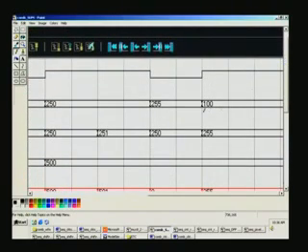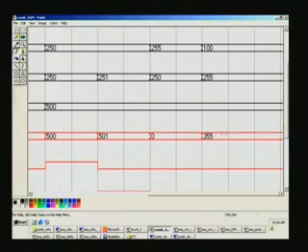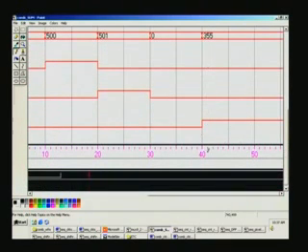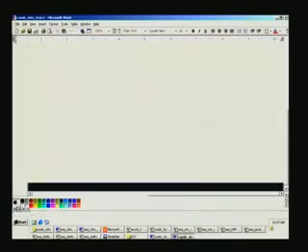So you can see the last value is 100 and 255. When you add, you get 355. That's sum, and this is less than the preset value here. Therefore, less goes high, right at that point of time, say at 49. So you can have a look at the test bench there.